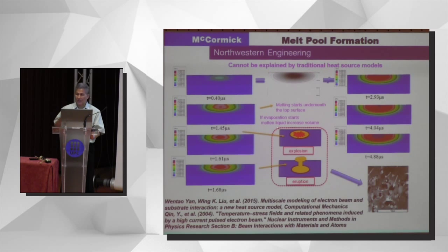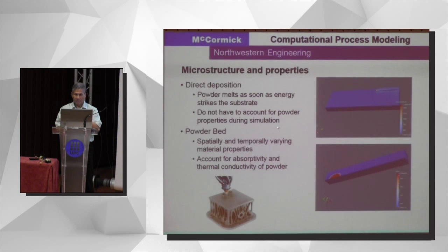I don't have time to go through how to design metrology, but that by itself would be a different talk. Okay. Now the second thing will be, given this heat source model, now I'm going to program the path. Okay, you can see here, I want to do it in real time, direct energy deposition, and you program the path, and I want to see the temperature distribution, the melting and remelting or solidification, because you go layer by layer in this case here. Okay. So we need to have a very fast computation, online computation, so we can do online monitoring of the system.